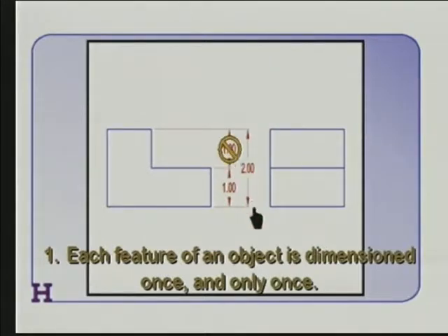The reason is because of the tolerances. Suppose that I put that back for a minute. Suppose that we dimensioned with what most people would consider double dimensioning. Suppose we put these double dimensions in here. How tall can this object be? Well, let's say that they all use the standard tolerance from a title block note that says plus or minus 10 thousandths.